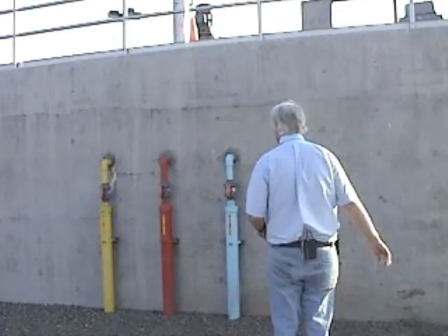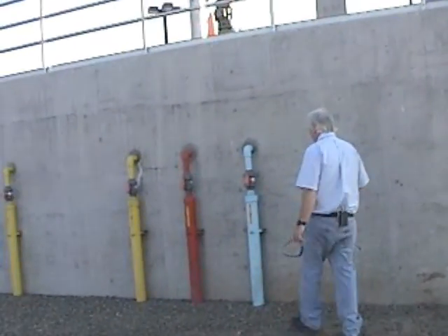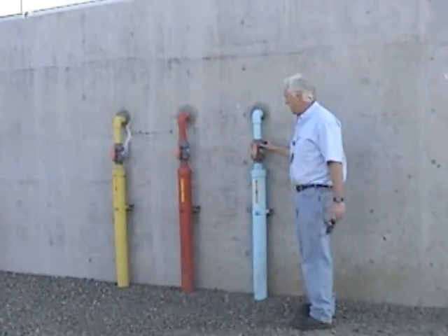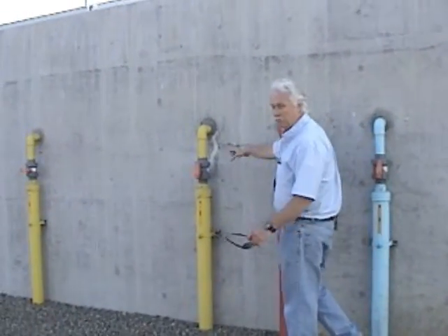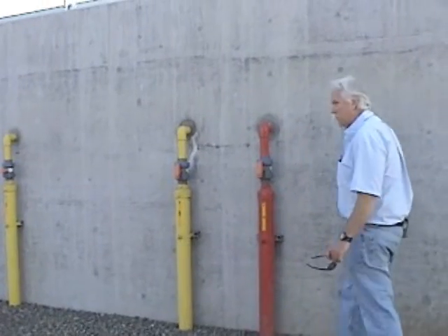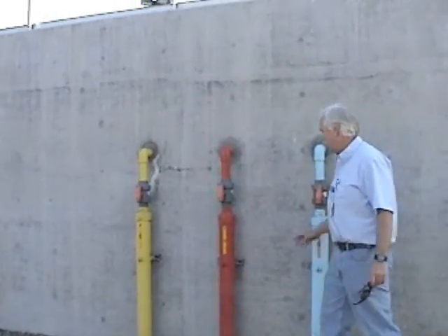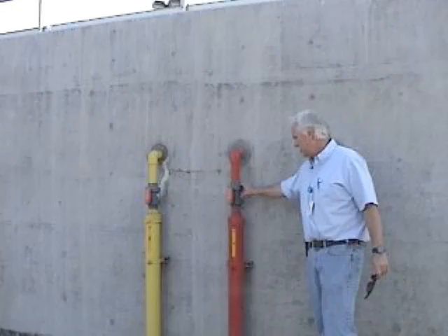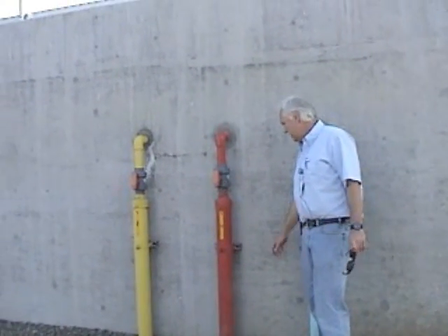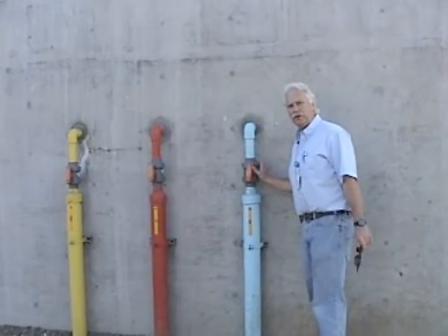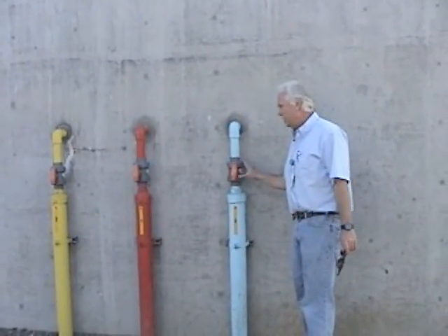This is the north side of the flocculation tank here at RP5, and we have the ability to put polymer into the flock tank. We can put alum into the flock tank, or we can actually bleach it. Our permit requires us to use a token dose of alum, so that's what this line is doing right here. We're adding a very, very small amount of alum to the filters. We haven't had to use polymer at all, but if we did, this would be the line that we would use.